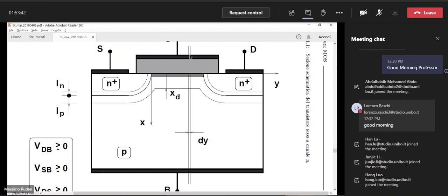And this elementary strip starts from the metal, which is followed by the insulator, which is followed by the semiconductor. And in the semiconductor, we have an inversion layer, a depleted region, and a neutral region. Okay. To calculate the current, we have to perform an integration over the horizontal coordinate y. So over a number of strips like this. Okay.